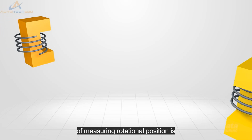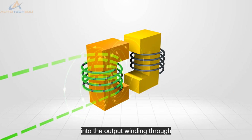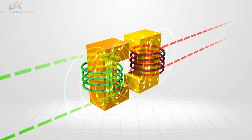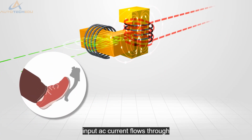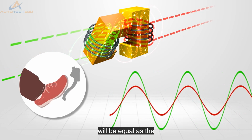Another way of measuring rotational position is by using inductive coils. An AC voltage is induced into the output windings through excitation of the input windings. The output voltage will vary based on the angle of the accelerator pedal. At rest, with no driver input, AC current flows through both windings. Their values will be equal.